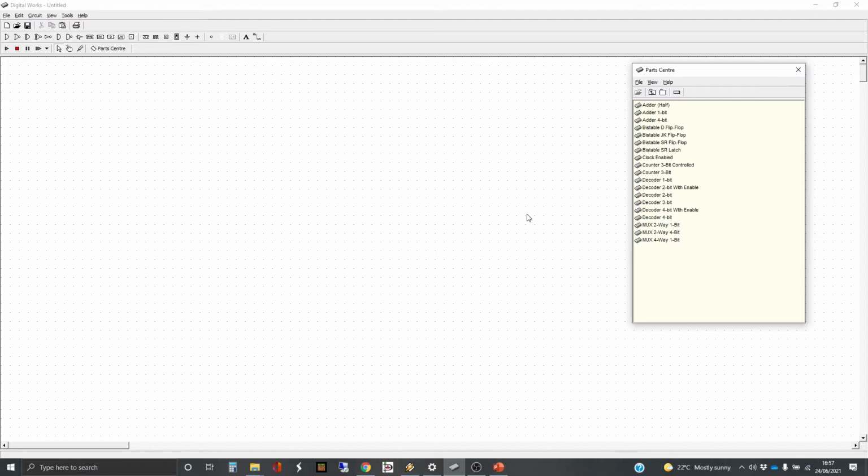There are various elements that we're going to need. We're going to need a 4-bit decoder. We happen to have one here that we've created in an earlier video. So I'm going to pull that in and rotate that so that it's... no, I'm not. I'm going to leave it that way up. And then we're going to have 16 discrete 1-bit inputs, but I'll wire them up in a little bit. And they're going to be wired up to AND gates.